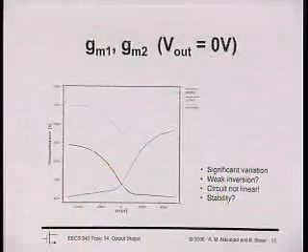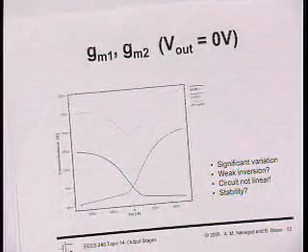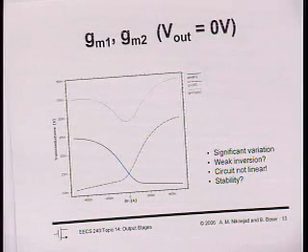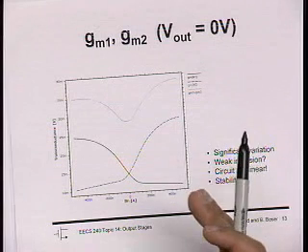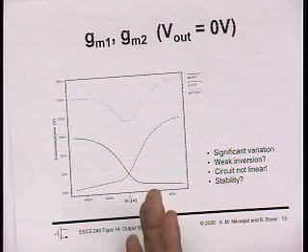The other issue to look at is how the GM of the circuit varies. If you plot it, because the currents are varying considerably, the transconductances of the output devices are varying a lot. And so what's the issue? Well, if you're swinging a large current, then the GM is changing, which means potentially the stability is changing. This is going to produce a pole.